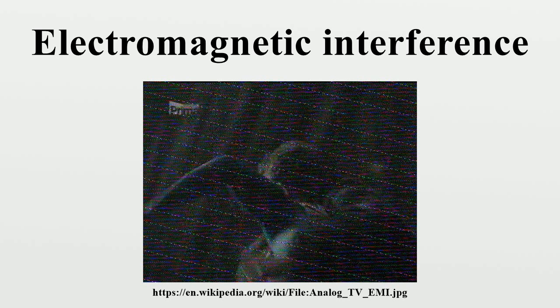Because of the added expense of shielding components such as conductive gaskets, the efficiency of the radiation depends on the height above the ground plane or power plane and the length of the conductor in relation to the wavelength of the signal component. At lower frequencies, such as 133 MHz, radiation is almost exclusively via I/O cables. RF noise gets onto the power planes and is coupled to the line drivers via the VCC and GND pins. The RF is then coupled to the cable through the line driver as common mode noise.